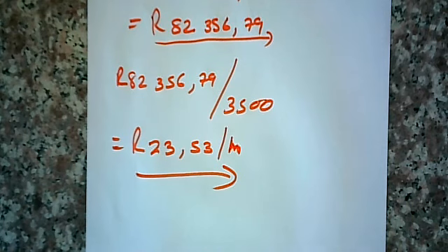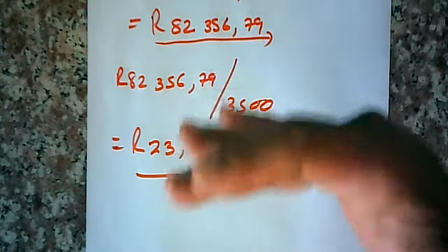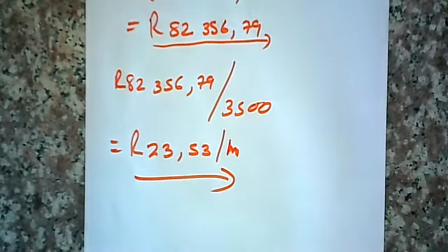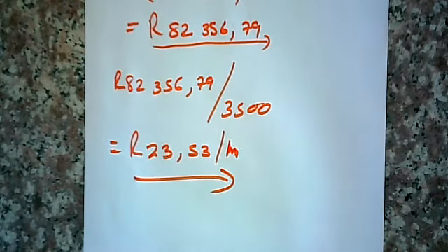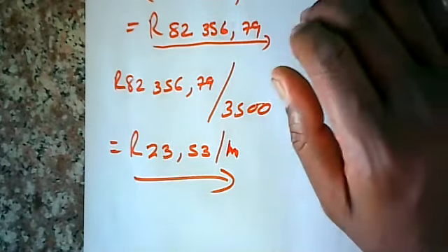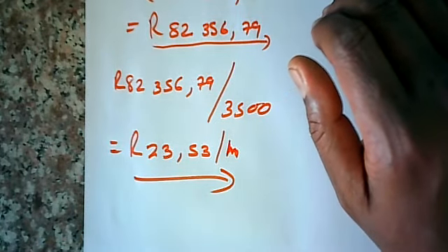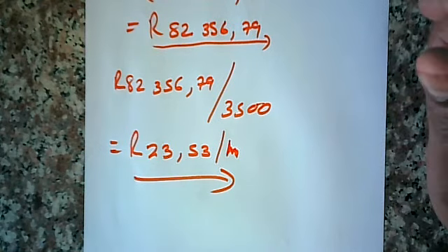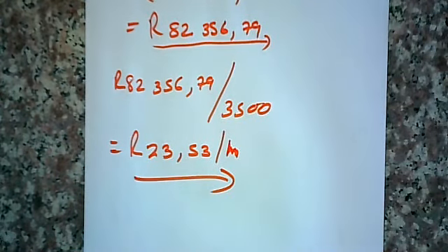Okay. Notice how we've broken down each of the activities and the plant and the cost of the pipe. And not too difficult, not too complicated. We found a cost per meter. All right, all within the ambit of estimation. You use bulking factor, you use overheads and profit, you use labor and artisans and the cost of it. You could use output of the machine, all within the ambit of estimation.